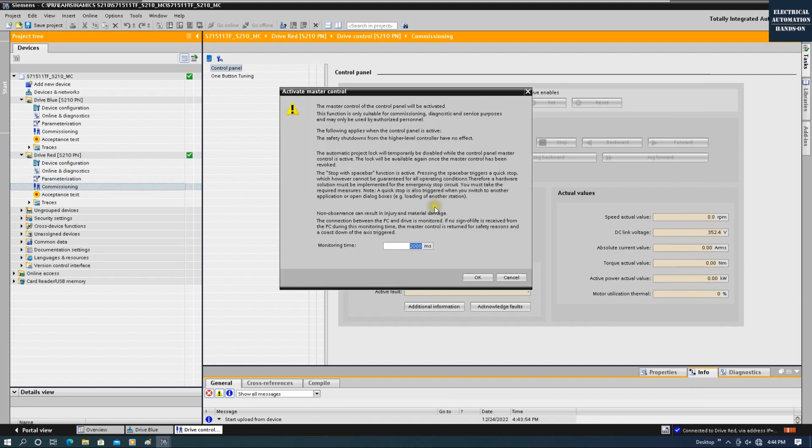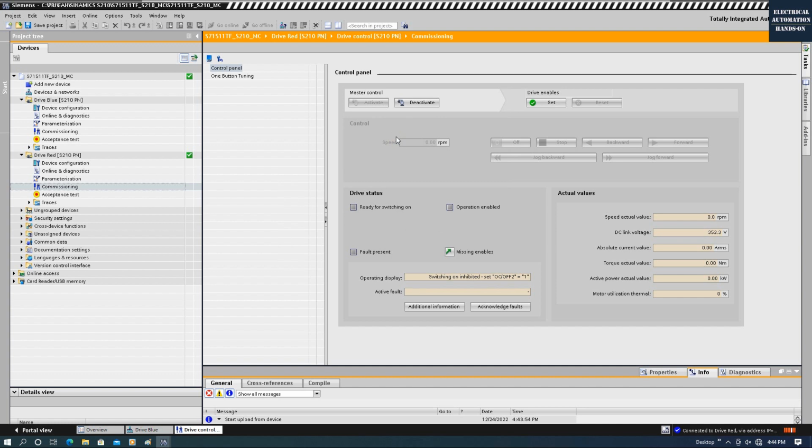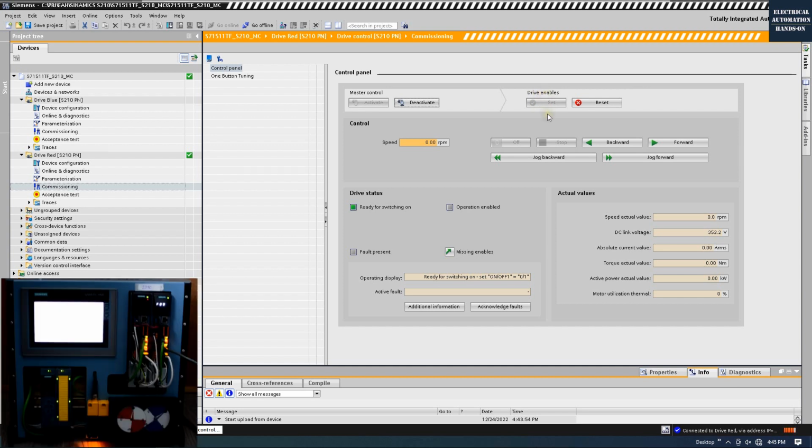And now if I activate this drive, okay, check out this message because now we are going to spin this motor. Make sure your outside is totally safe. And once I set, that means we will power on the drive. Now without any controller yet, we directly communicate with this motion drive. Now, this is the servo drive, and now the ready signal is on, and without any wrong message here, we can set speed, for example, 60 RPM, and we can click this jog forward.